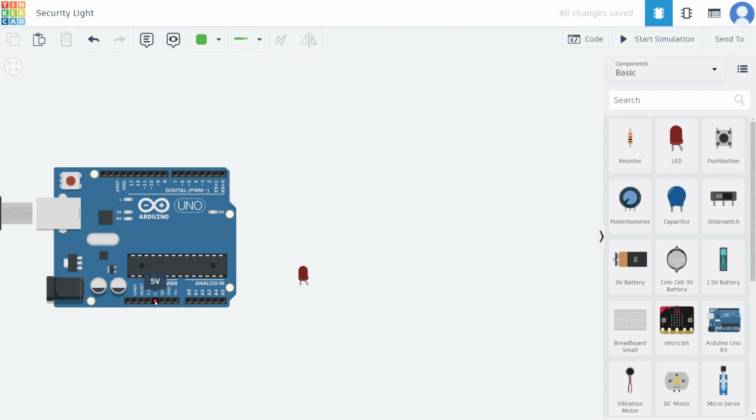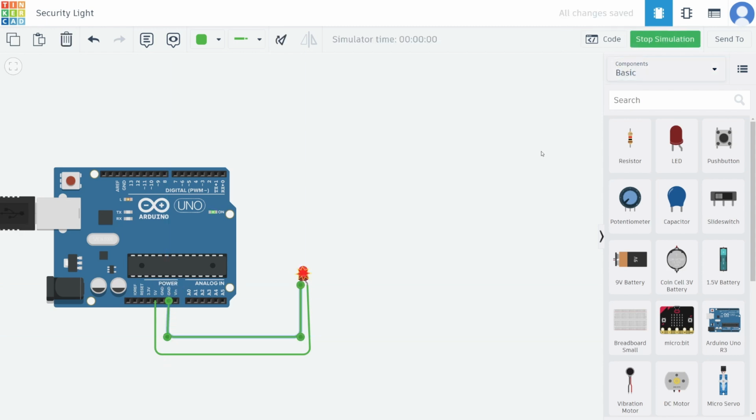And I have a feeling we're going to discover something else a little bit surprising about the LED. So we connect the 5 volts positive to the long bent edge here and the other side to ground. And let's click simulate. Now you'll notice here that it did work this time. However, the 5 volts was too much and it overwhelmed the LED and blew it up. And in real life, that would probably mean it flashes very bright for a second and then never works again,